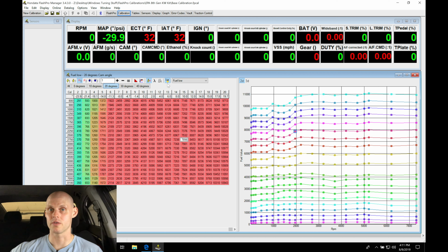If you need to do a hard flash, if you want to turn something off, you could turn a table off, you could then do another hard flash, you could turn a table on. Anytime we make any changes to the live tuning options, we need to hard flash it again. So it is that 90-second flash. It takes a little bit of time. It's a waste of time. So we need to be diligent about this and do things that make sense. So we want to have our low speed fuel and ignition timing tables editable, as well as our variable cam table for the low cam.